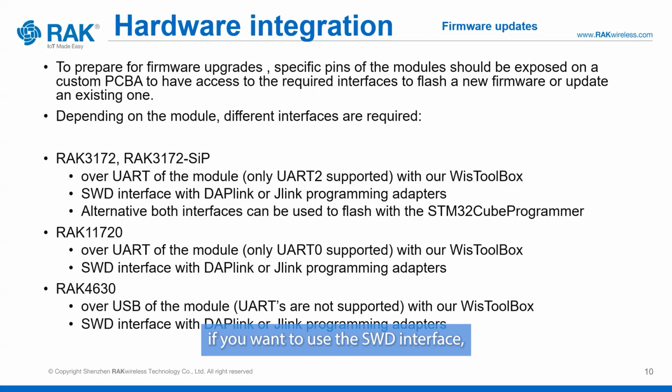If you want to use the SWD interface, you have to expose different pins, which are the clock, the data, the reset line, and ground to be able to use a DAP-Link or a J-Link programming adapter.